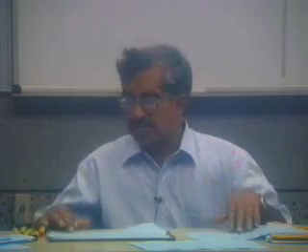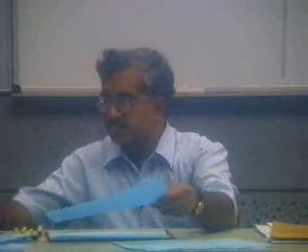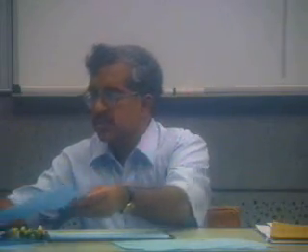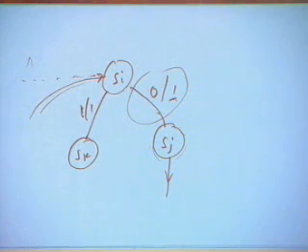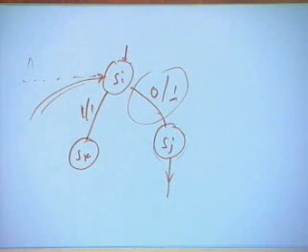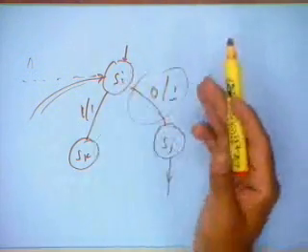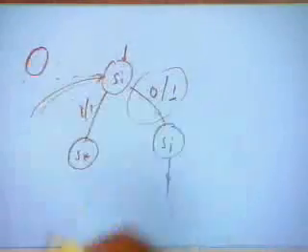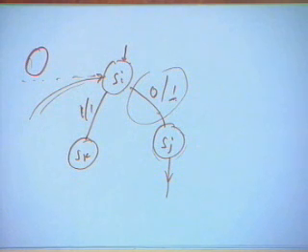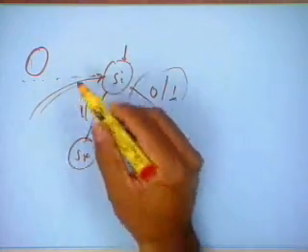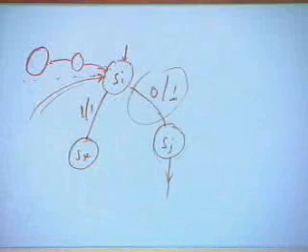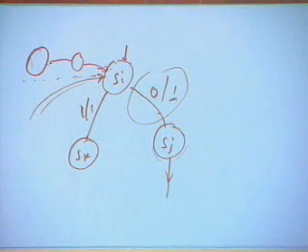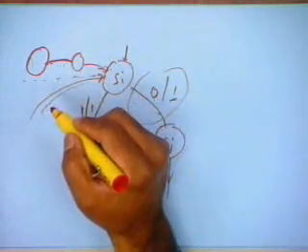So let me just repeat what we said over here. The process is: I may be in some initial state. First of all, I have to somehow reach SI, and I have to look at the output to be able to reach SI. So now I apply a homing sequence, but because the homing sequence is not going to give me all the states, I may still end up in some other state. Of course, I have confidence in saying that I have come to this state, but this state may not be the same as the SI state. So then I have to apply a pattern and assume that these transitions are correctly getting executed. Or the other method is to first verify this transition. Start from where you reached.